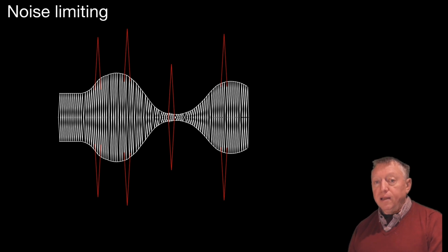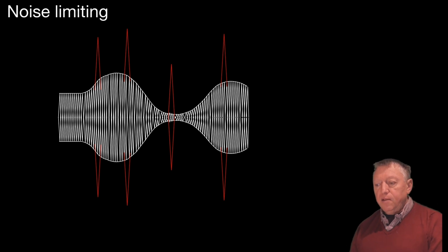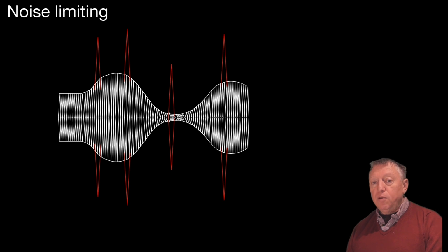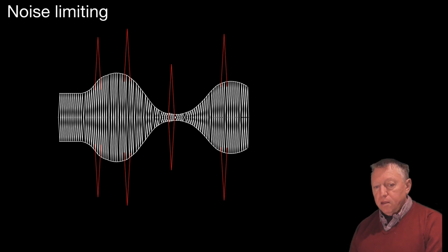Maybe a distant lightning storm causing interference on the HF bands. And these spikes can have considerable amplitude and can be many times the amplitude of our wanted signal, and can therefore be very annoying because, particularly with headphones, they could cause hearing damage and make it difficult to listen to the wanted signal. So we look for a way to limit the damage caused by these noise spikes.